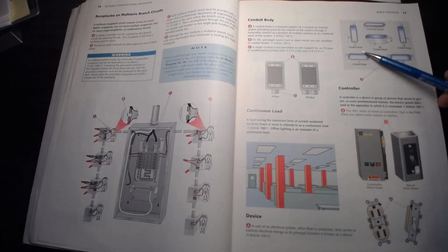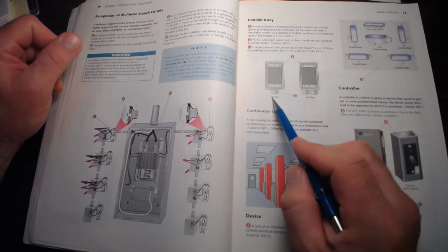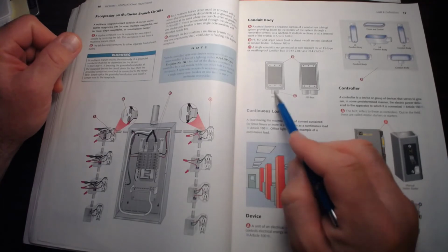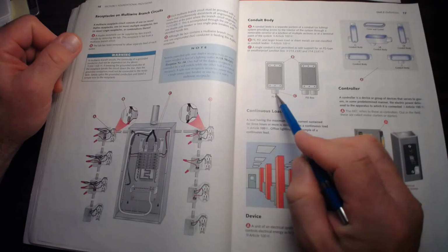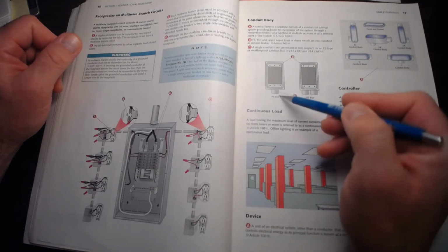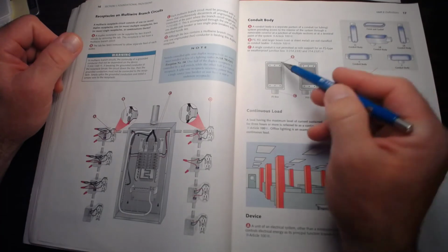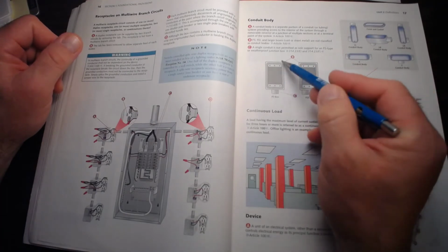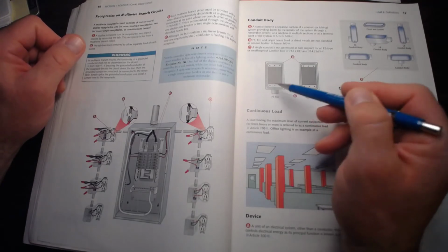It's really important when you get into industrial, because then you will know how to lay this out, write up your material list, and go buy the material. These boxes here are called FS boxes because FS is a single, and then FSS has two hubs. There are a lot of different FS type boxes out there, but these are cast steel boxes, and with the proper cover they can be used for explosion proof.